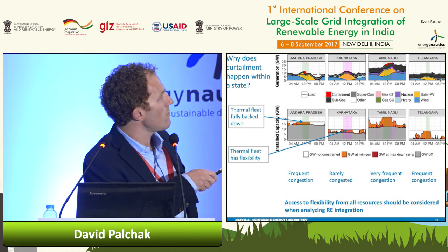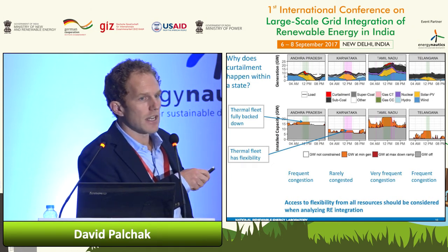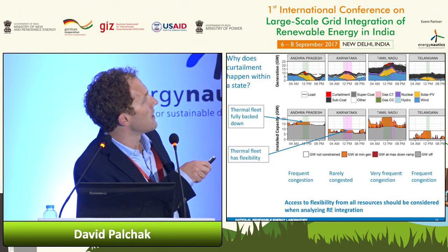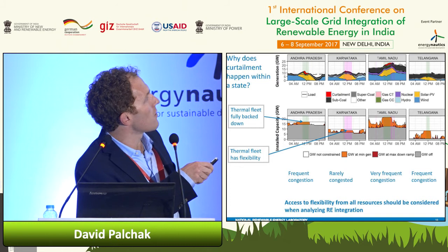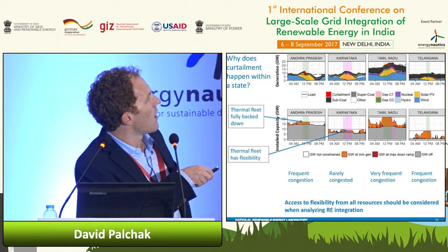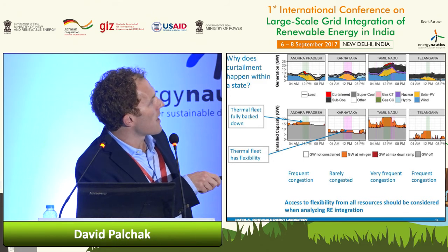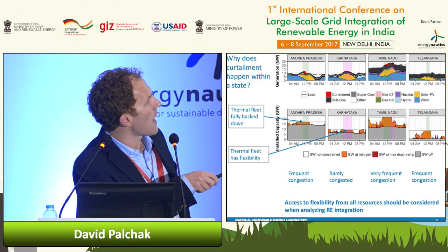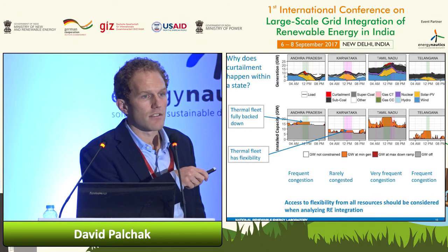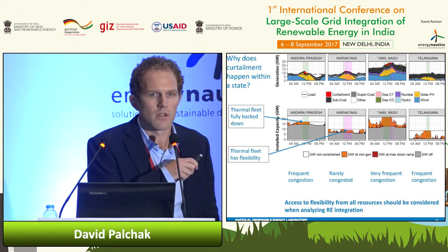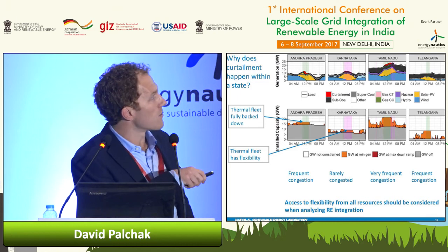So all of the orange can't move down anymore. It's at its min-gen, and there's nothing online to turn down any further. And you can see if you look at the dispatch stack, this is actually a very small capacity of coal that's still online. One other point about this is what you see in red here, and that means the coal plants are actually turning down as fast as they can. So they're at maximum ramp down. That would also be considered a potentially inflexible state as well.